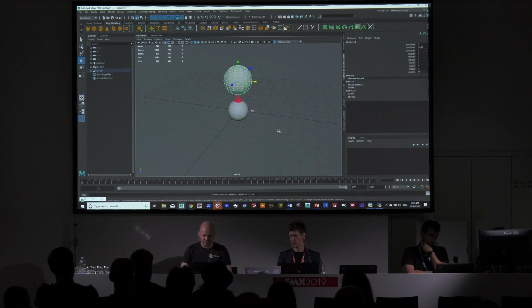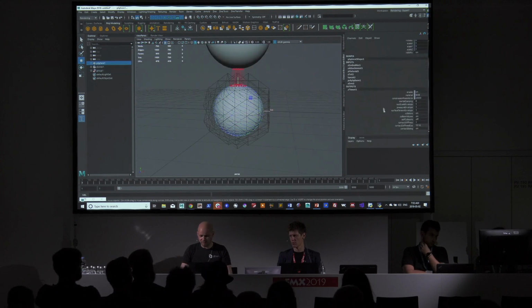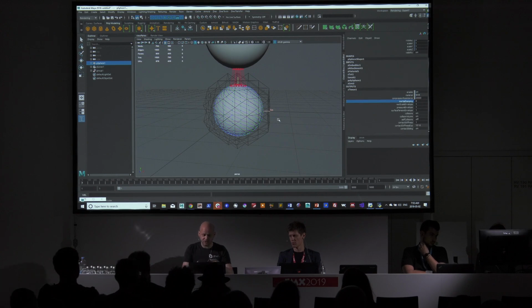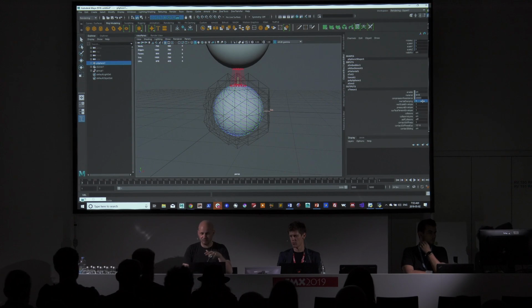I'll just demonstrate the inertial damping quick too. Per element, or per tissue, you have this attribute on it called inertial damping, which is right there. When it's set to 0, the tissue receives the full momentum of the system. If you set it to 1, the affine modes of deformation, the things that really relate to the position, the rotation, the shear of the object, end up getting solved quasi-statically. But all the higher frequency stuff is still fully dynamic. So what's cool with that is the object could whip around at whatever speed you want. It's not going to get any momentum. But if you whack it into something, you'll see wave propagation because it hits it.